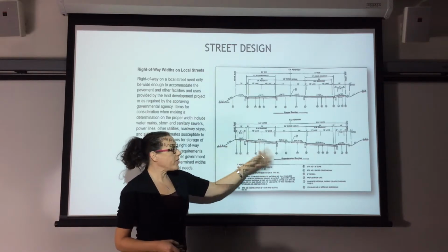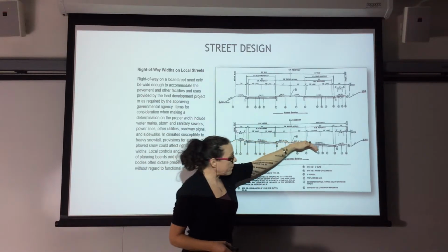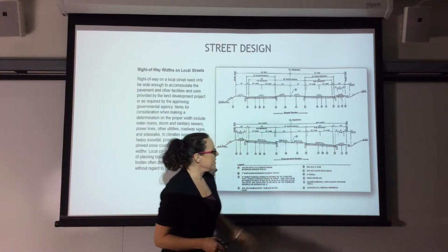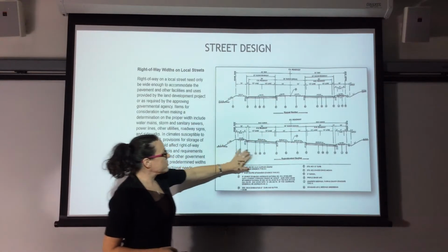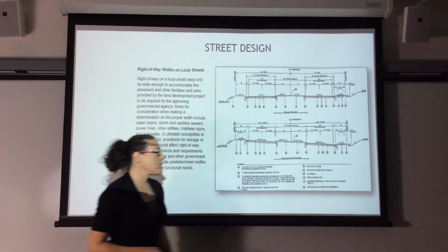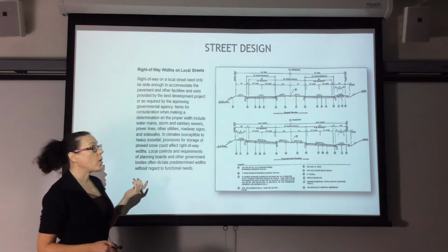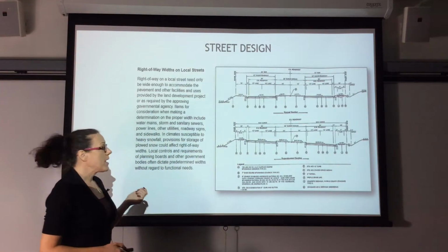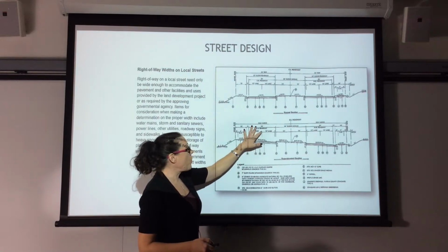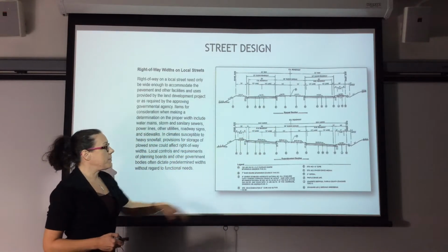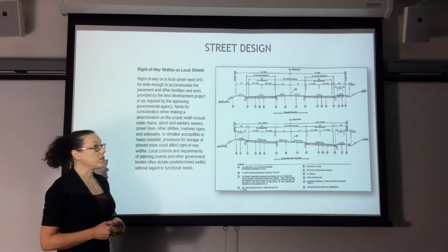It'll tell you what the risks. You can see this is actually super elevated, so you can see that it slopes across. What these little dots are representing, and you can't really see them, is what that material is made out of. You'll also be told what the slope is and how wide. These are the typical designs you see in a construction plan.